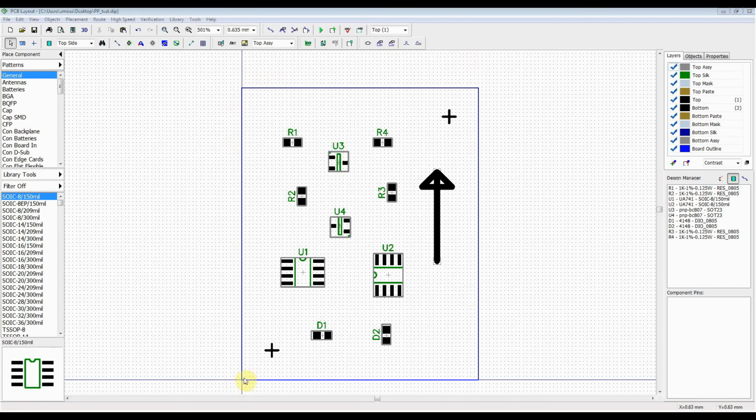Board outline, obviously. I'll place the origin generally down the bottom left hand corner. It's something that I do as default, and it's best practice. That way, if you've got any screw ups, you know that the origin is always that point there, so you can align all your different layers all the same.